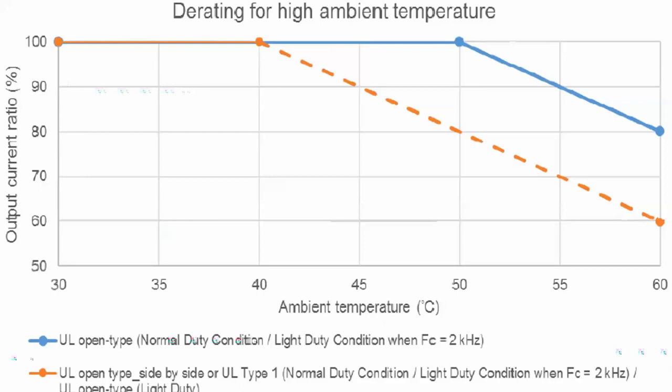So you will again have to take the rated current of the drive and multiply it by the derating factor for 8 kilohertz. Depending on the model, we'll have to derate by either 87% or 84%.